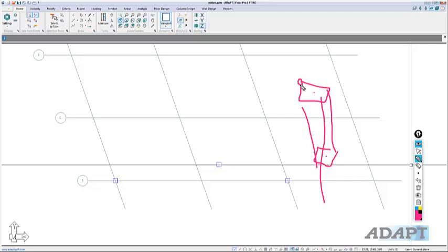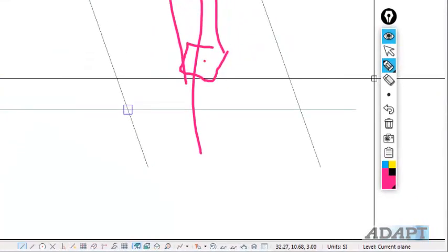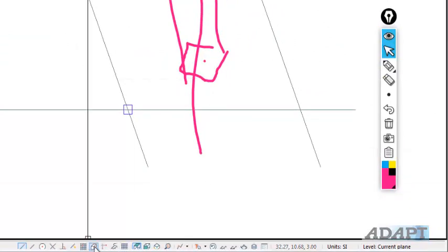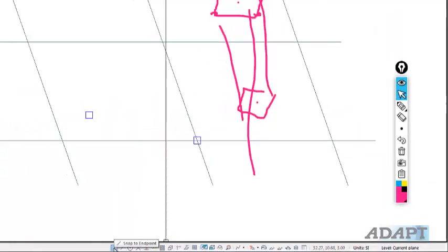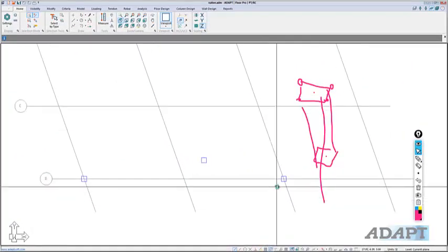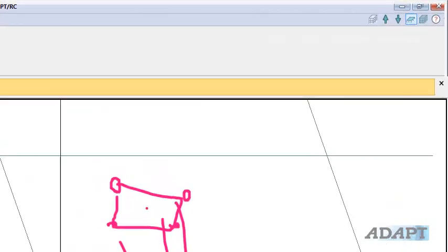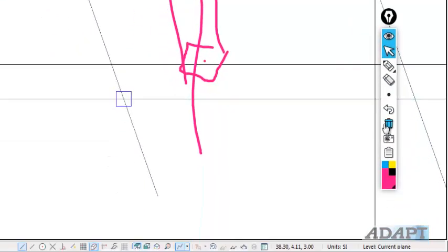If you want to snap on a corner 1, 2, 3, or 4, we have to actually turn on Snap to Vertices of Components in conjunction with Snap to Endpoint. And then that would allow us to actually snap. If I draw a line, I can now snap to these corners of a component. So using these tools properly will really help and cause less frustration, if that's something that the user experiences when you're trying to draw and align things and even model component to component type of connections.